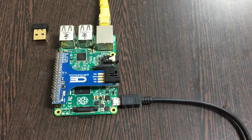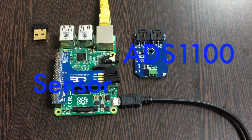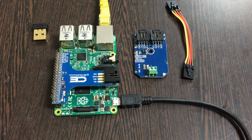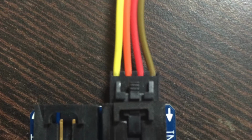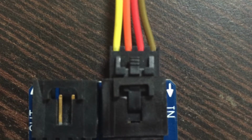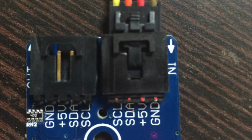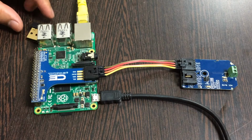The next thing we require is our sensor, that is ADS1100. Now this here is a connecting cable. This connecting cable is very useful in making the connection between the sensor and the I2C Shield, and while making this connection, make sure that the ground terminal of the sensor is connected to the brown wire of the cable, and similarly to the I2C Shield, just like that. As we are done with all the connection setup, what we require next is to have a look over the code.